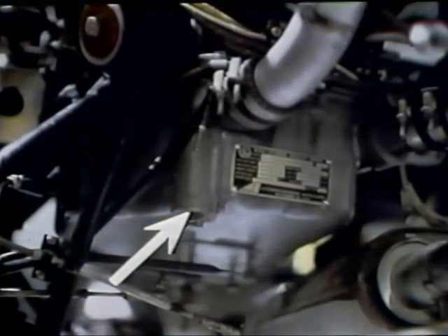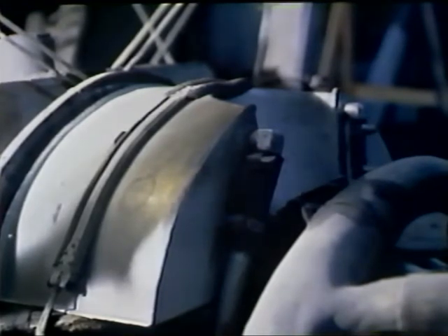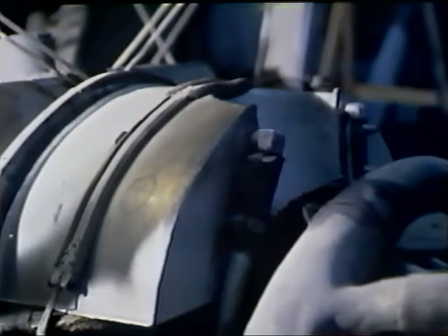If the entire oil supply is contained in a sump attached to the engine itself, the engine is said to have a wet sump lubrication system. But some engines require more oil than can be stored inside the engine. This is why a dry sump system is used predominantly in radial engines. In this system, the oil is stored in an external reservoir. It flows by gravity to the pressure pump, and after circulating through the engine, it is returned to the tank by a scavenger pump.